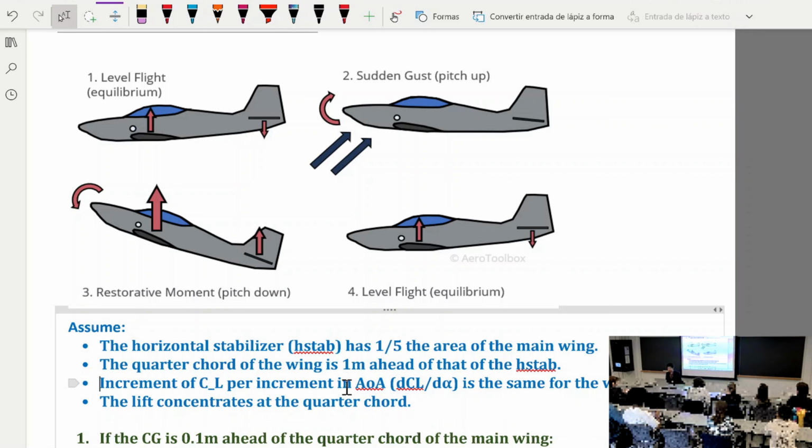So if you touched the thin airfoil theory in Unified or elsewhere before, you're going to know that for very thin airfoils and very small angle of attack, the same constant, dCl d alpha, is 2 pi, right? In reality, for real wings that are not infinitely thin, and even before the wing stalls, this quantity is not going to be too much different from 2 pi.